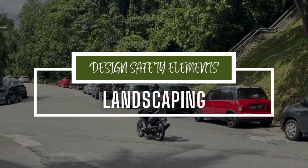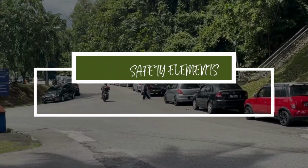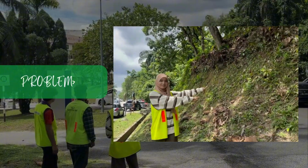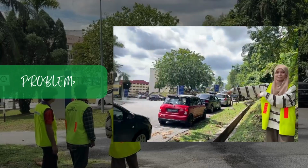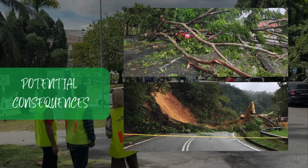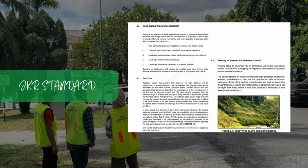If JKR road landscaping guidelines are not followed, several risks arise. Trees planted too close to the road become fixed object hazards, increasing accident severity if vehicles leave the carriageway. Overgrown or leaning trees can block driver sight distance and traffic signs, while slopes without retaining walls may erode or fail during heavy rain. This can lead to road damage, lane closures, and high maintenance costs. Overall, ignoring JKR guidelines compromises safety and the long-term reliability of the roadway.